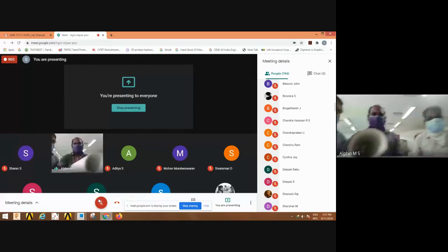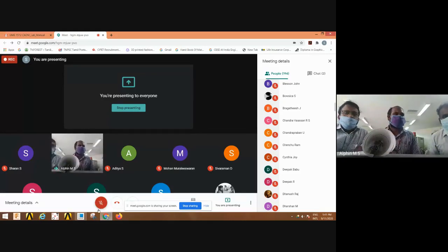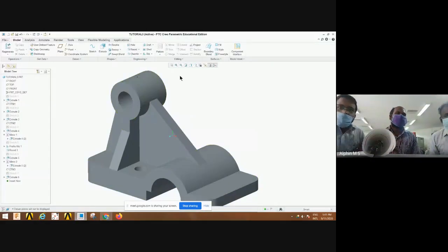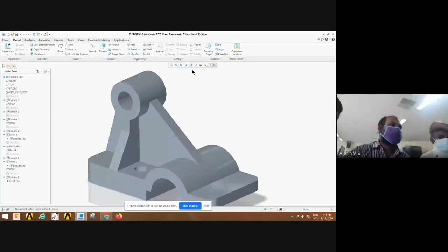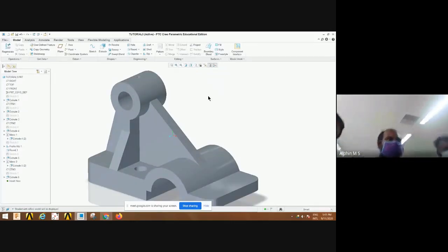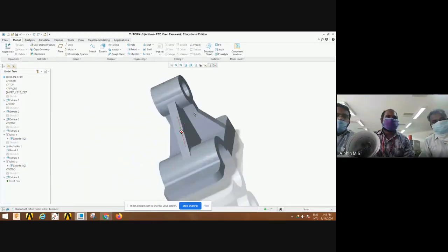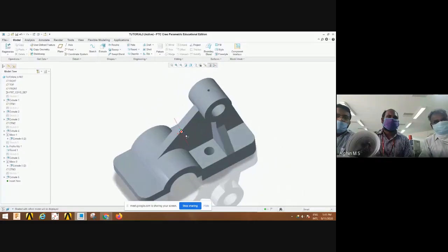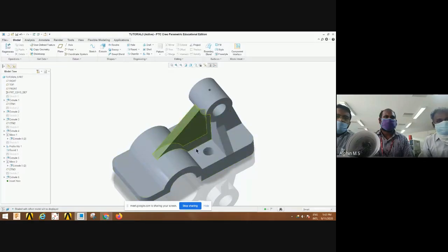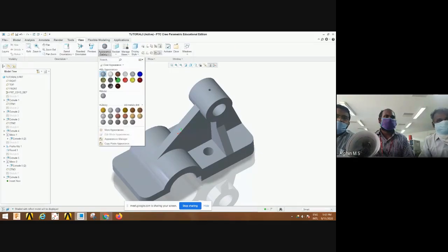So what we have done is we created a plane on the top and we extruded the whole circular feature down, and the hole went right through the cylinder which is placed horizontally. Once it got extruded and the material was removed, that created a hole. We removed the material which was overlapping, so it created a hole. What you might have tried is drawing a circle on the surface of the cylinder. That kind of thought is where most of you might have got stuck.